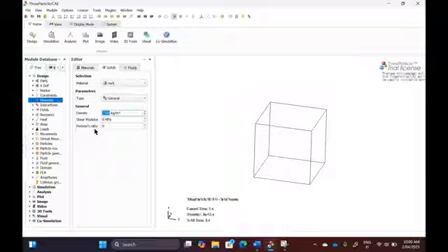Shear modulus, please stick in the range between 10 to 100, probably 150, not the real physical one, because I had colleagues putting in something much too high. Your computation will crash and it takes too long. Start with, I don't know, 20. Please don't go below 10 or 5, that's the lower limit, because it's very complicated.